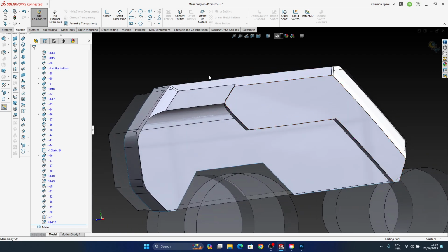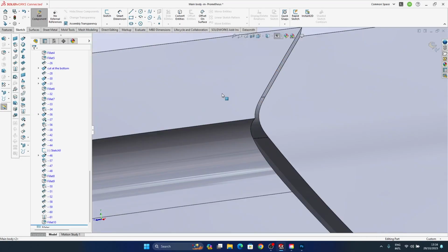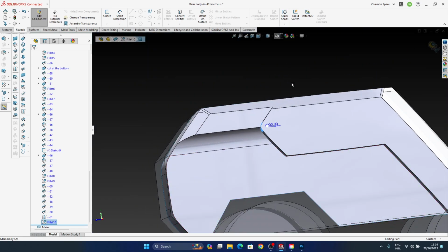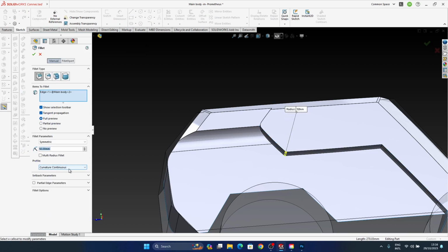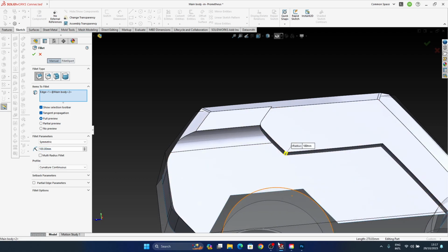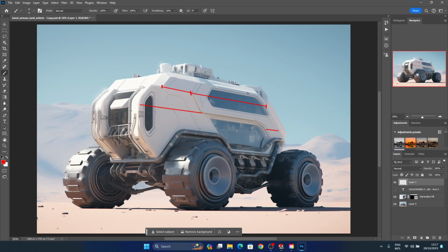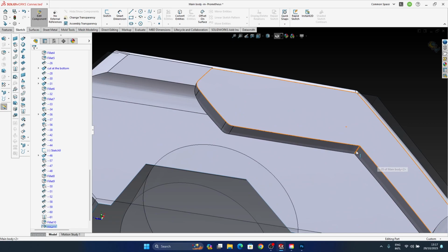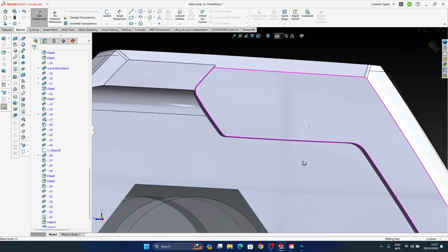Right, so we want to have a fillet like that in there, and I think it was 200. Yes, so it was 200 in there. So here probably somewhere around 100 should be just fine. No, actually it would be somewhere around 200 again. So 200 as well. What do I have? So here I have one that is quite large, so it should be somewhere like around 500. There, that's cool.